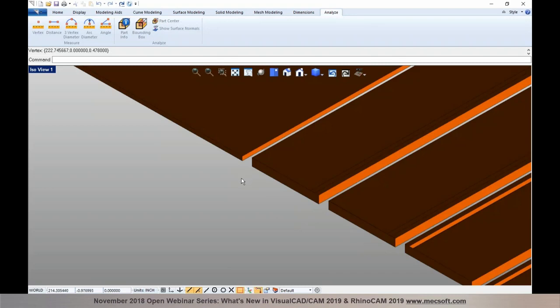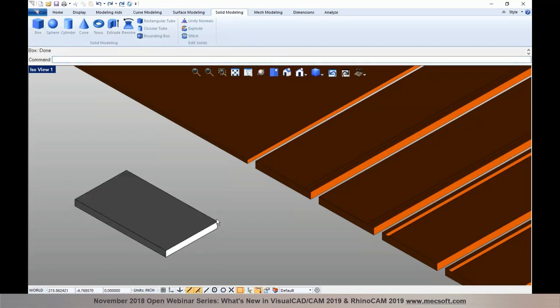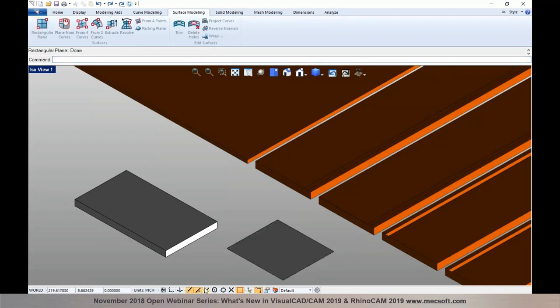There have also been changes made to the near and end snaps, so those will automatically continue to work with solid and surface geometry. So if you have a solid model that's created in here, or if you have a surface model, you can still use your near and end snap, and these will automatically be able to snap to the near points or the end points along a vertex, along the edge or the face edge of the model. So that's also an improvement, to speed up the performance of the snap objects.